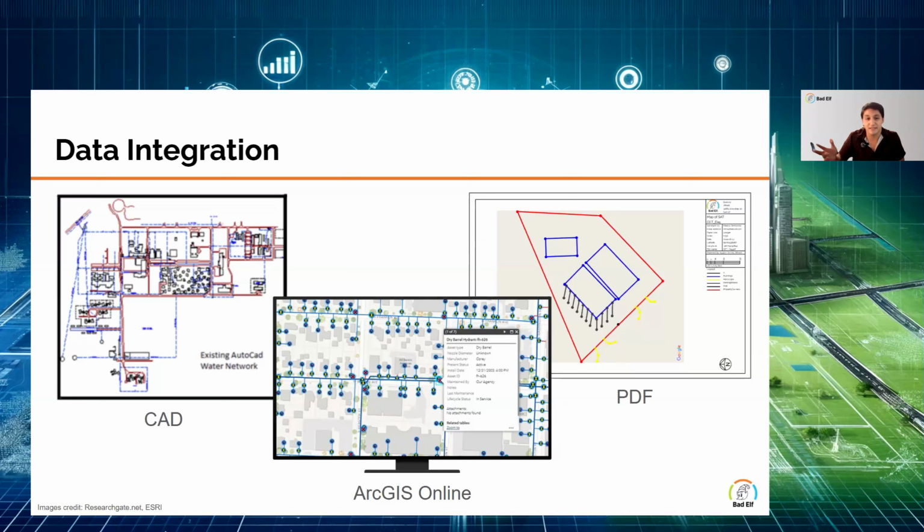But yeah, so these examples show the flexibility of APGLOS and what it brings to field data collection. It makes it much easier to adapt to the specific needs of a project or a team, or to integrate data that you've received, or to give it out to someone who needs it. That's because with APGLOS Survey Wizard, the field data is simple to reference and integrate, right? The software supports imports from shapefiles, KML, and DXF, and allows for exports in all those same formats, or as a PDF with the customizable title block.